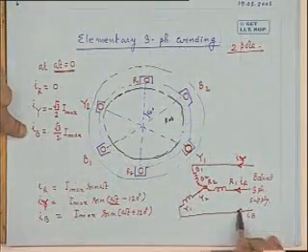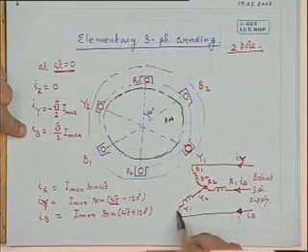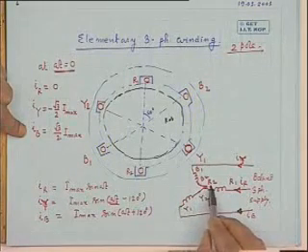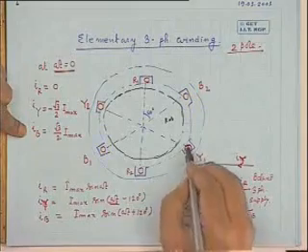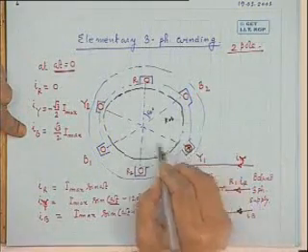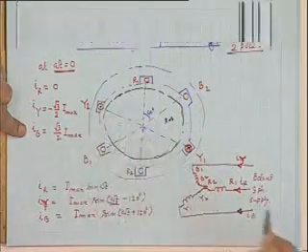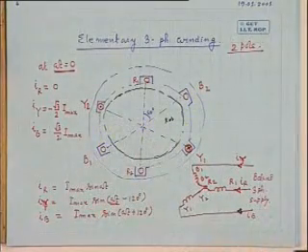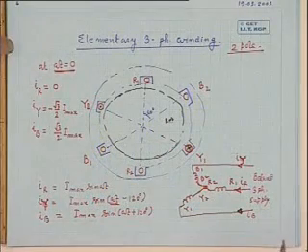R phase is not carrying any current. So in Y and B phase, let us say, it is IB in this direction and it is positive, meaning really it is entering through Y1 and leaving Y2. So in Y1 I should put a cross and in Y2 I should put a dot.